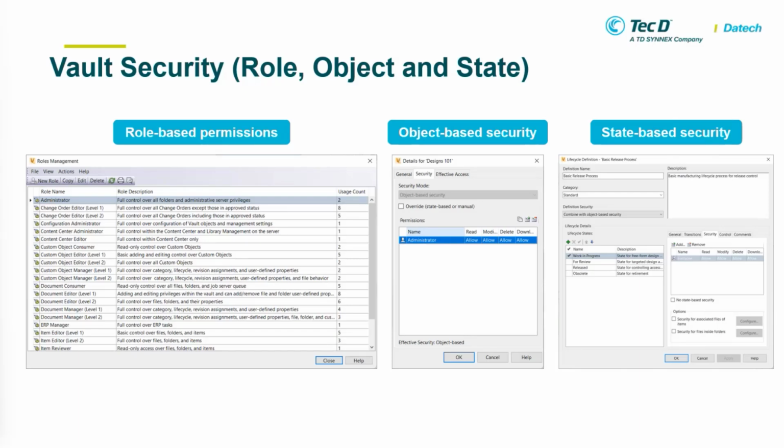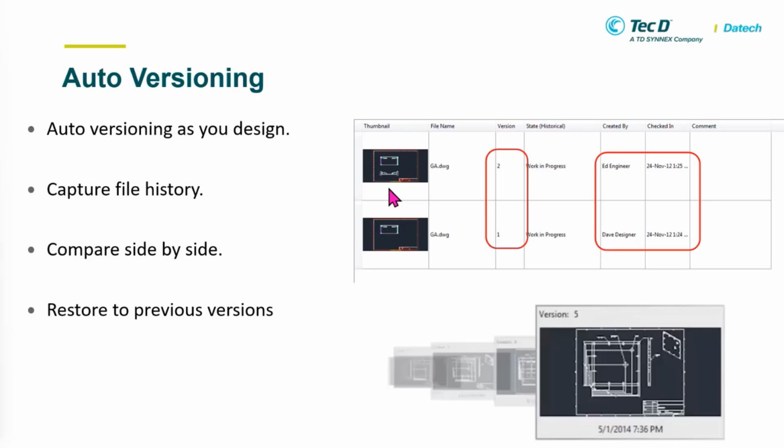So when it's in the review state, other people or other engineers, even myself, are not able to edit, okay? Until my manager who's doing the reviewing approves or rejects the drawings. Then it goes to the next state. If he rejected the drawing, it will go back to work in progress. If he approved the drawing, it will go to the next stage, maybe a release. Okay, this state is customizable depending on company requirement.